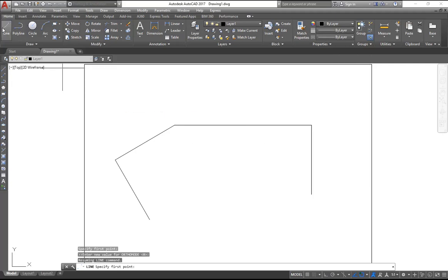So I'll pick a point, I'll pick a line. So I will just have the endpoint already selected. Now you can see when I begin to have this problem to know whether my line is straight or not, just enable the orthogonal mode so you can be having your perfect straight line. So the first segment there is 30. It's good to follow the segmentation because it's going to help you in completing the drawing properly. The next segment is 35. Just type 35, press enter. Okay, that's 35.